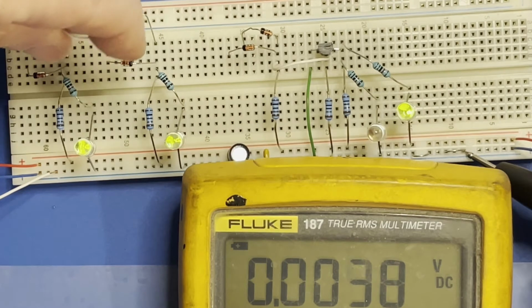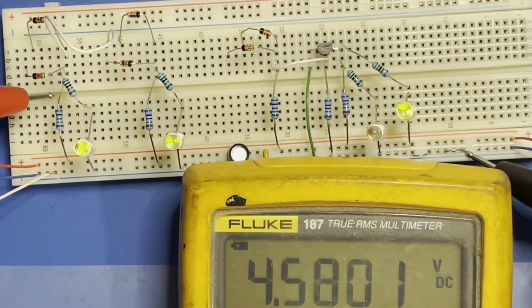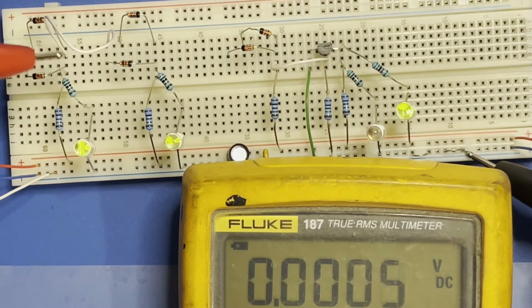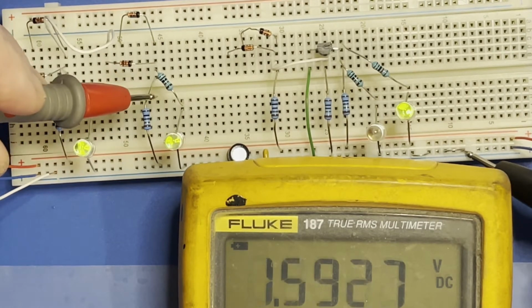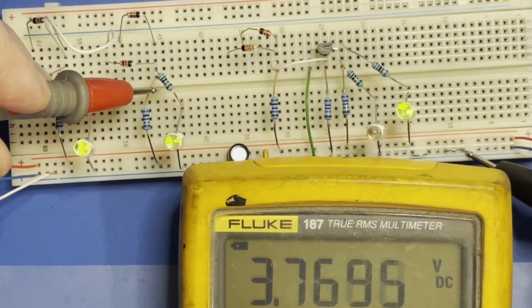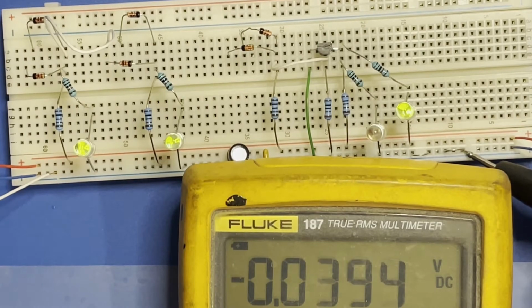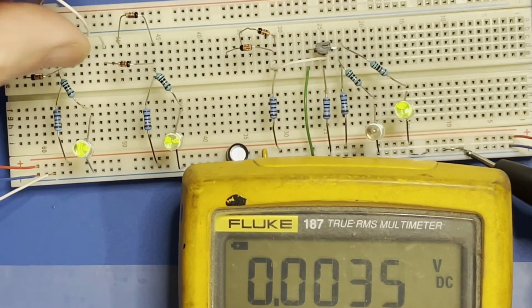That level, rather than being a nice clean switch between high voltage and low voltage, is now half supply, because that resistor connects in series through a diode to that resistor that goes to the opposite supply. So no longer got a high or a low level, it's just halfway. So they are not cascadable gates.